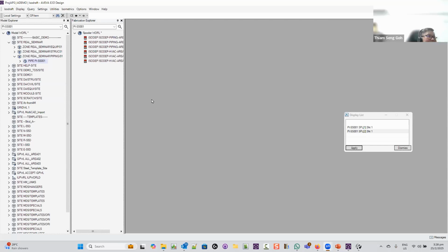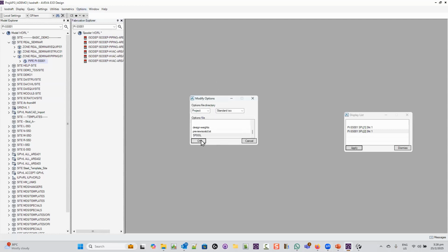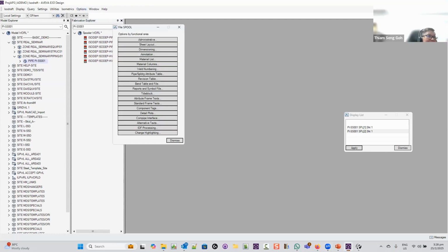Yeah. So, I don't know, are these drawings for fabrication, or could there be another level of drawing of shop fabrication drawings? I'm looking at this spool isometric, still isometric, basic isometric. Is it a fabrication isometric? You see, for our fabrication, our people will need to know each pipe cut length. Okay, yeah, that's why somebody asked where's the cut length. So basically, if you go into here and somewhere inside here, you have the cut length table.